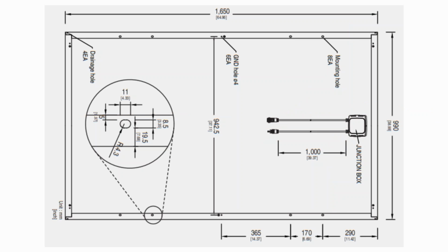But, and this is more of an advanced installer issue, managing these cables gets messy. And so every installer has their favorite cable management techniques to do with these things. Sometimes they're longer and you can do fancier things with your cable management than when they're shorter. Such as on a 72-cell panel, the panel itself is a little longer, so to be mountable in landscape, the cables themselves are a little longer, and that gives you just a little bit more length out of them to do some cable management.